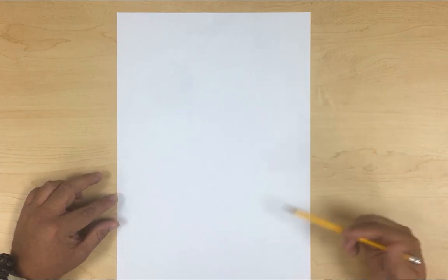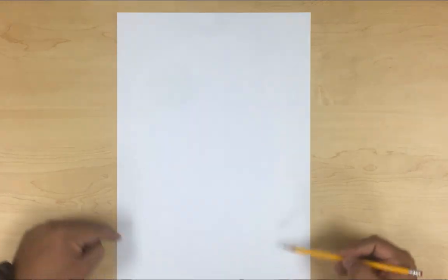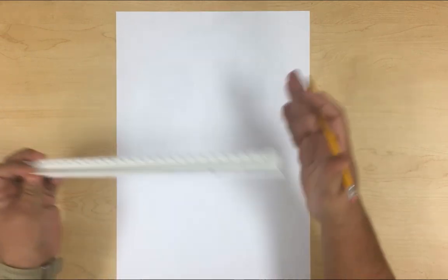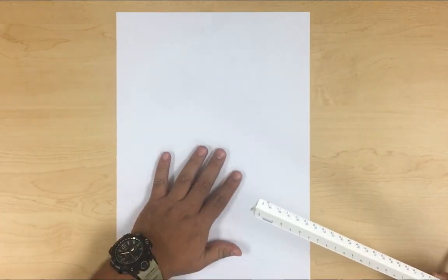The size of the lot is 64 by 95. Okay, so it's 64 by 95. So that's the first thing we need to draw on our plan, so we know exactly where our lot is located. The first thing we need to do, and again we're going to do it with a 1/8 scale, so we can draw the whole site plan on a B-size sheet, which is 11 by 17.